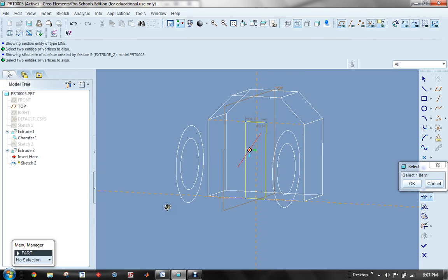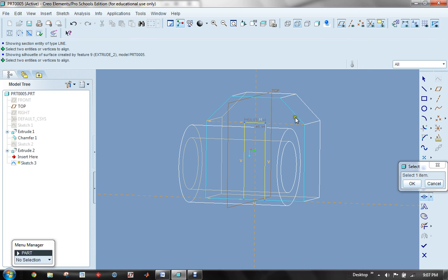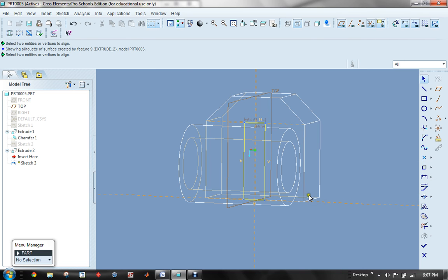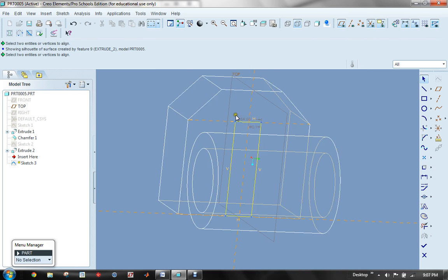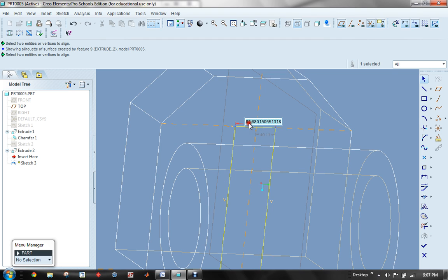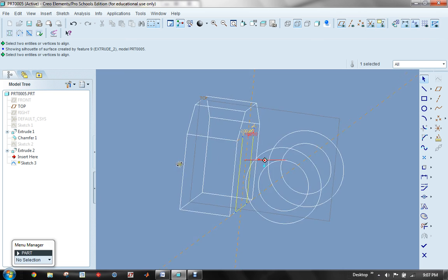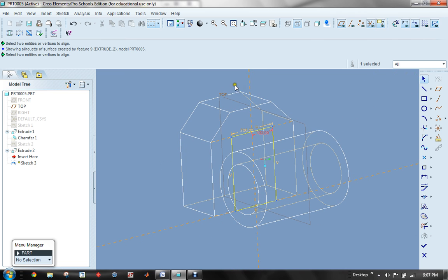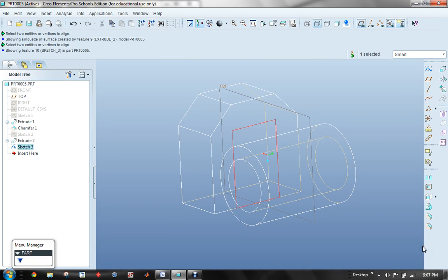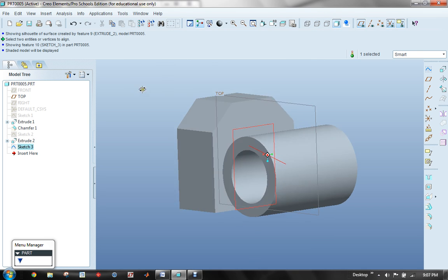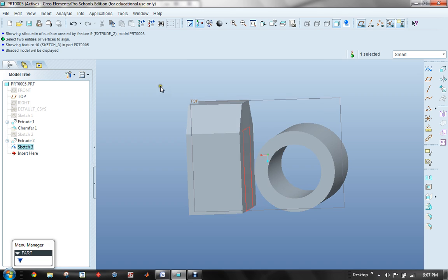So once I've done that, I'm going to cancel out. I'm no longer putting constraints on. I'll come back in here, make this 200, and I'll make this distance 100. Alright, so now I've made my sketch, and I'll say that I'm done. Now I'll go back to the solid view, because now what I want to do is extrude this, but I have an issue here.